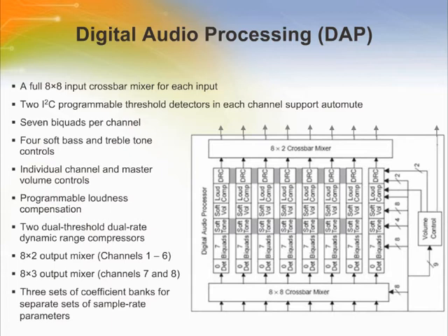The 32 kHz to 96 kHz configuration supports 8 channels of data processing that can be configured either as 8 channels or as 6 channels with 2 channels for separate stereo line outputs. The 176.4 kHz to 192 kHz configuration supports 3 channels of signal processing with 5 channels passed through or derived from the 3 processed channels.